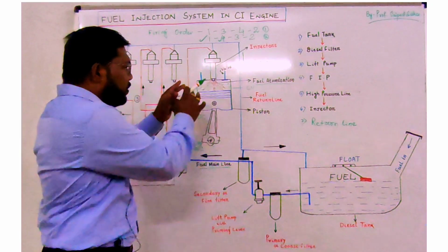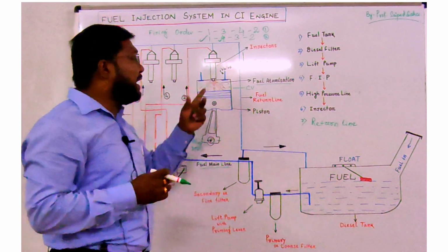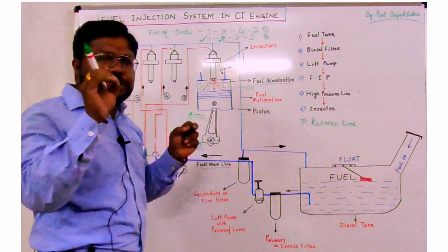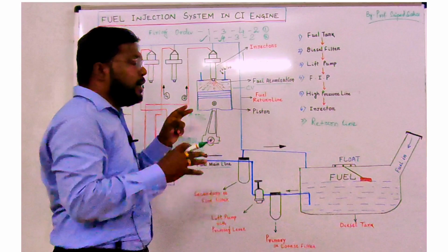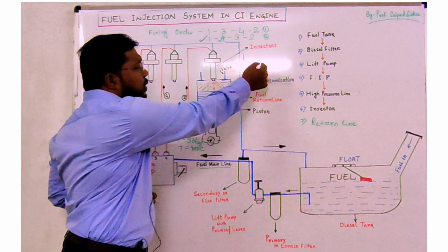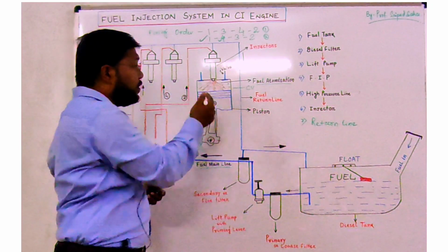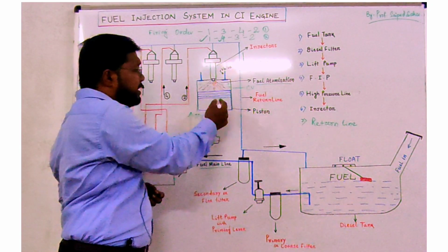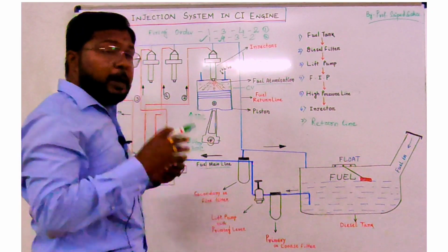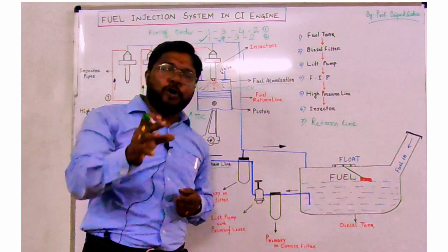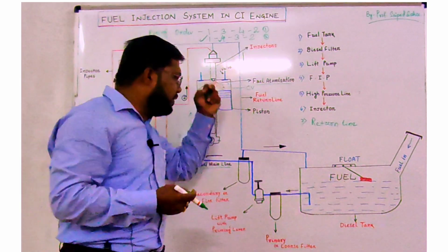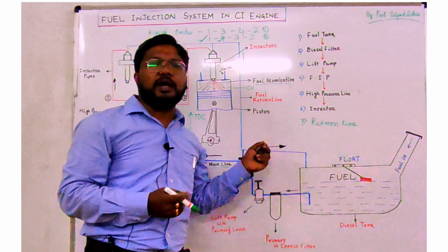That's why the pressure is very, very high, so that the fuel is more atomized, with more tiny particles of fuel spread into a very good flow pattern. So the fuel's surface area is increased, so it can vaporize very quickly and is able to burn by itself. That's why complete combustion is available, more power is generated, more fuel economy, good engine noise, and less pollution, less emission you are getting.